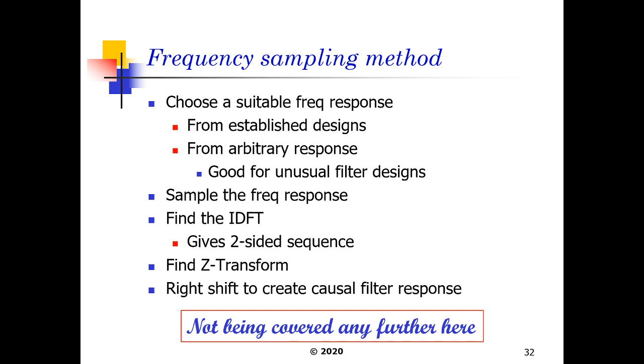So recapping what we did in this lecture, we basically saw that for FIR filter design, we need to obtain a symmetric sequence. And that means we start with the ideal low-pass filter response, and then we multiply the ideal low-pass filter response, after we know the number of samples and we obtain the vector values, by a window function, which is typically given. You are required to remember the equation for the ideal low-pass filter response. Once we obtain the vector values for h of n, being the low-pass filter frequency response, and the window function w of n, we just multiply each of those vectors together. And the multiplication is done by the indexes. So the -4 index will multiply by the corresponding -4 index, and so forth as we keep on going.